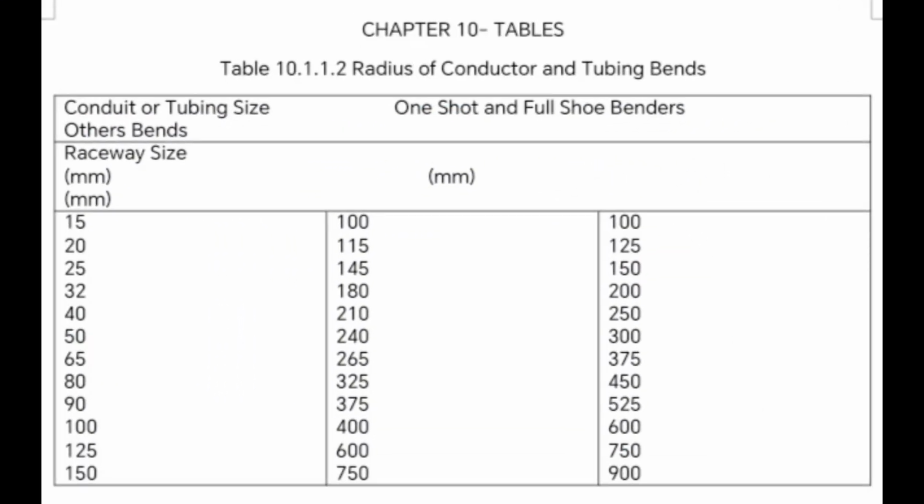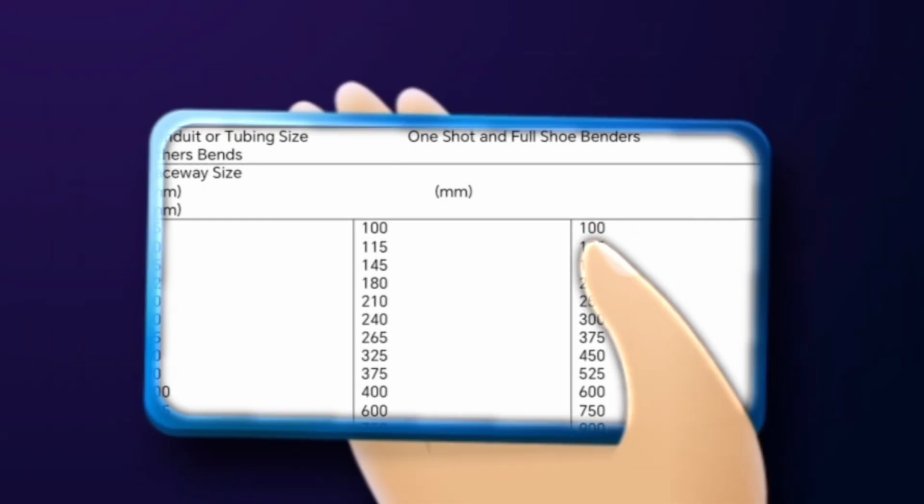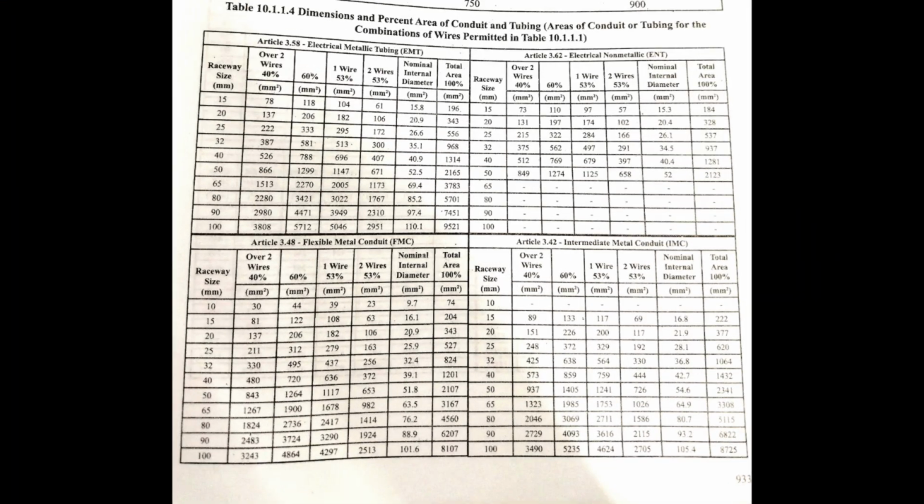In slide 8, ampacity and conduit fill. The current carrying capacity, or ampacity, of wires listed in Chapter 10 assumes a specific conduit fill. If you put more wires in a conduit than specified, you must reduce the rating, the ampacity, of those wires to prevent overheating.